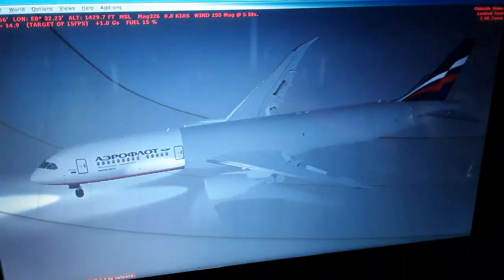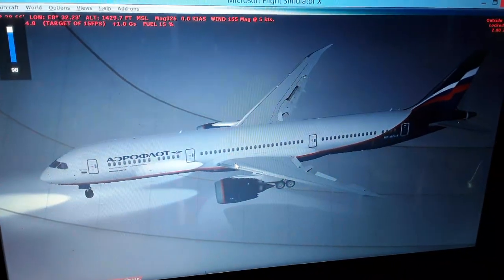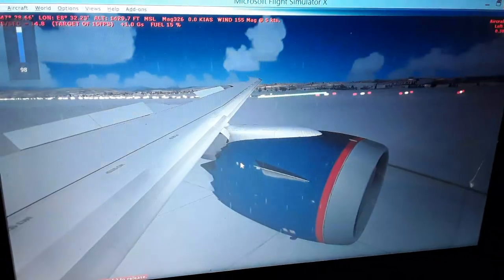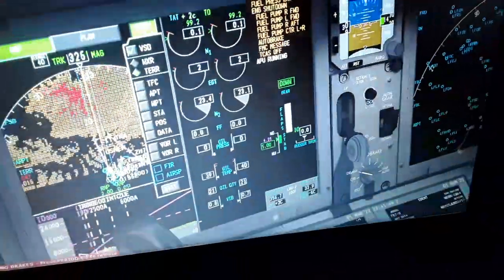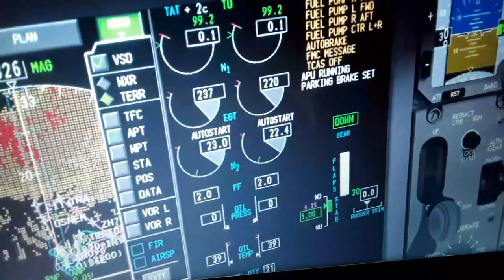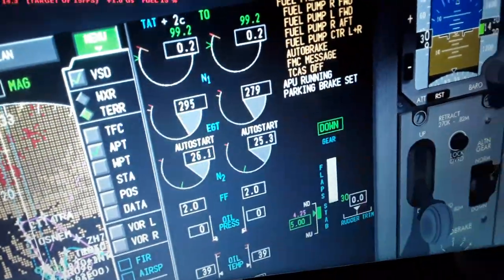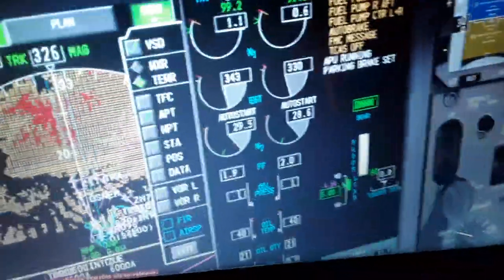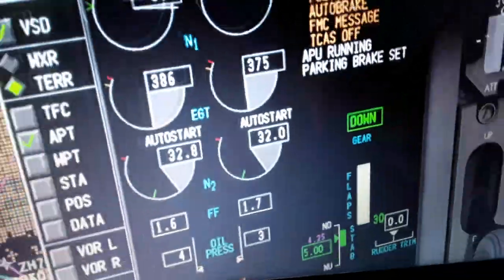So we have only pressurized air right now. So above 20% we can let the fuel control on, fuel flow on, both left and right, fuel transfer. So we have the auto start. Now we have both pressurized air and fuel into the engines, the auto start.